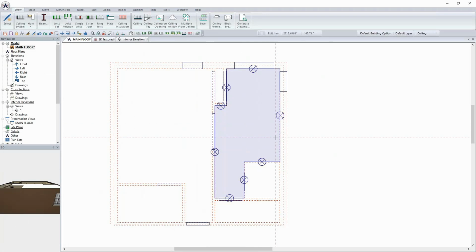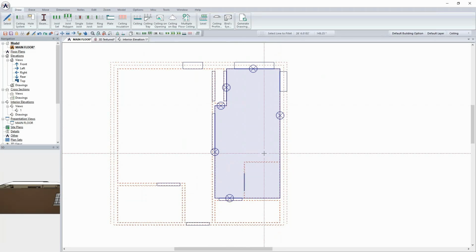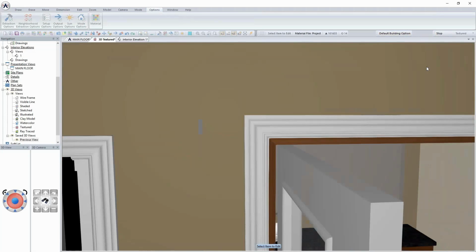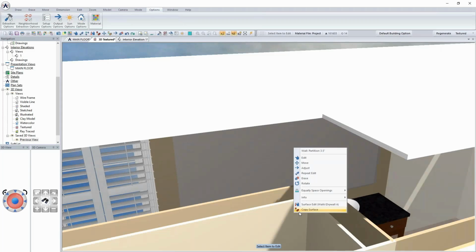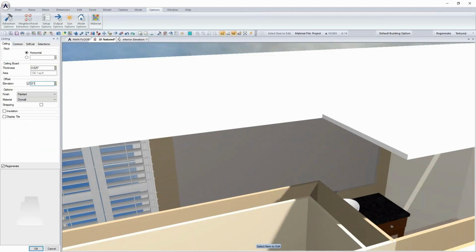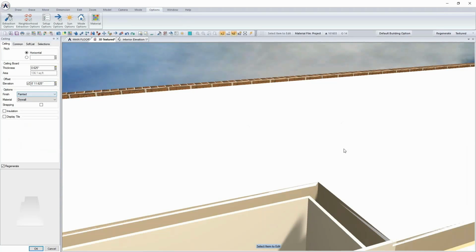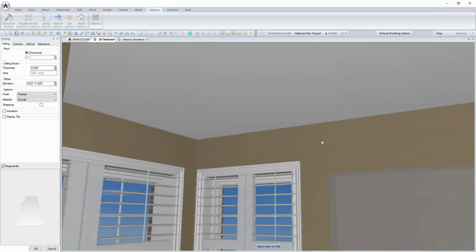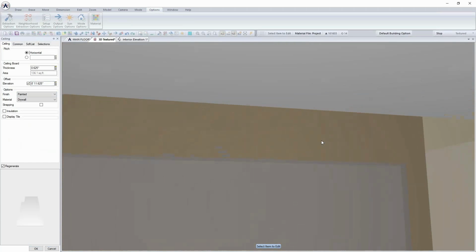Now, I'm going to have that ceiling run all the way across. It went around the shower wall, so I did a fillet and just filleted the 2 corners. Let's take a look here. We've got an 8-foot wall and 8-foot, 11.65 inches to push it down. And so as I take a look at that ceiling now, we can see it's pushed to the top of the wall, okay, and the fillet has it carry all the way over the actual shower itself.